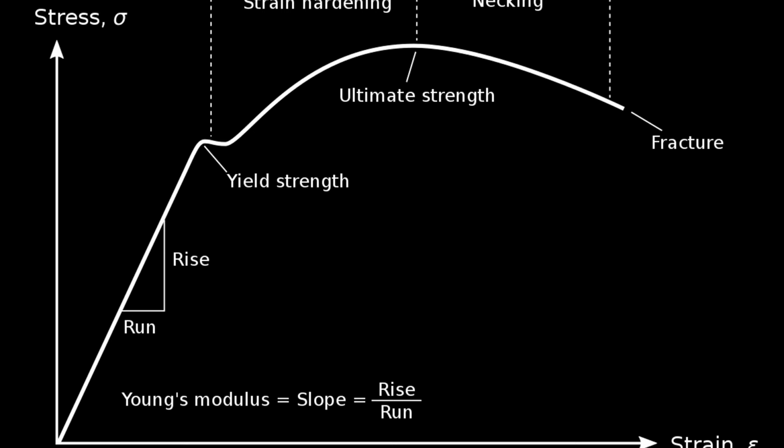First thing I'm going to do here is show you a graph. This graph is really important to understanding what the values on the right side of your screen mean, and I could make this a super long segment, but I'm going to keep it short so you can get to the actual simulation part. So the most important point on this graph is the yield strength. Without knowing what that point means, you don't really know what the information the simulation is giving you means.